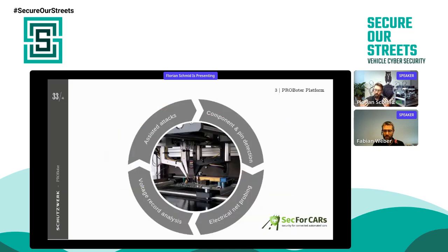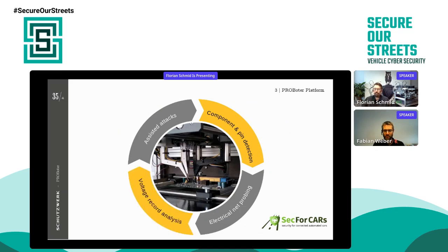So for all those targets, I would like to give you a bit more focus on 2 of those tasks. First is the component and pin detection, for which we use the camera systems, as well as the voltage record analysis, which we use for the evaluation of the voltage signals that are occurring on the PCB.